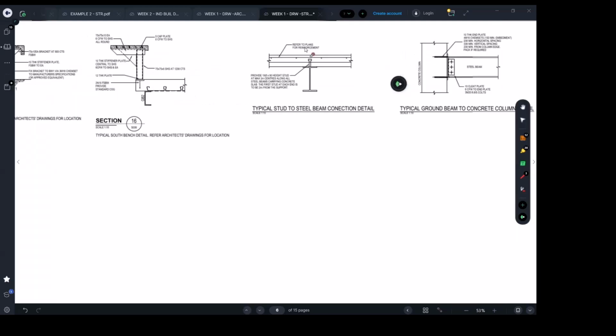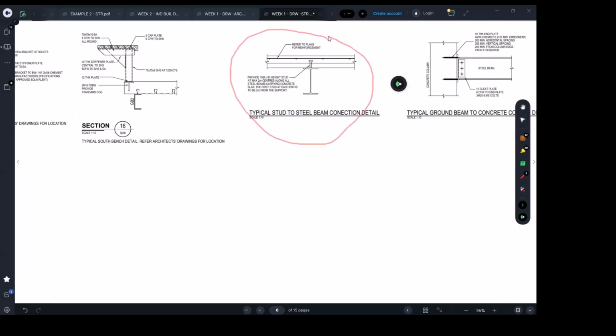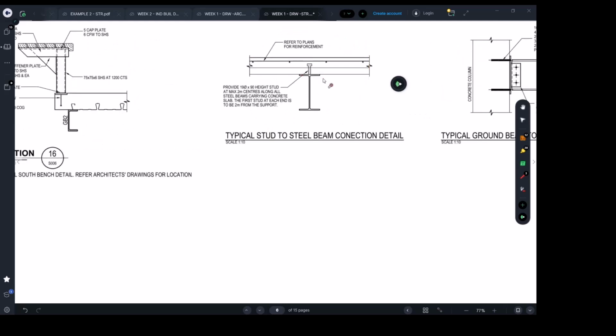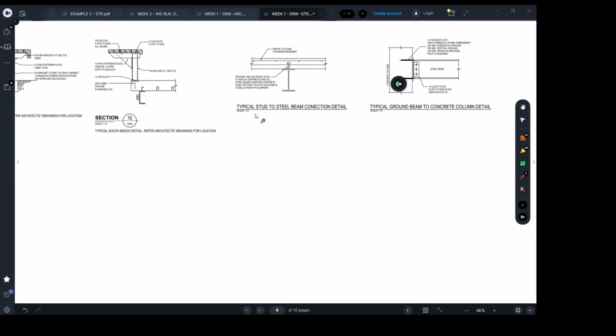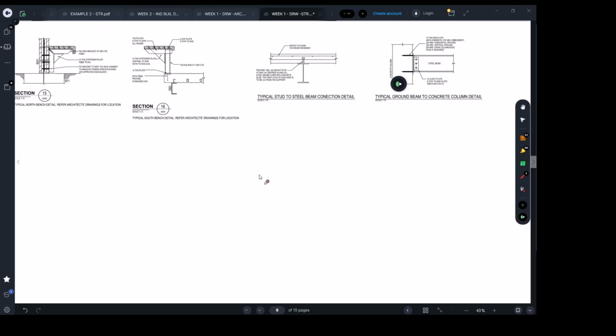Maybe he's gonna say, or she's gonna say, it is about this, so that will be acceptable. This detail is related to number 6. Sorry, to the slab construction. It just tells you how we're connecting. However, I will not agree, actually, because we don't have steel in the first floor. So I don't know actually why this was used. Can someone tell us why they selected number 6?